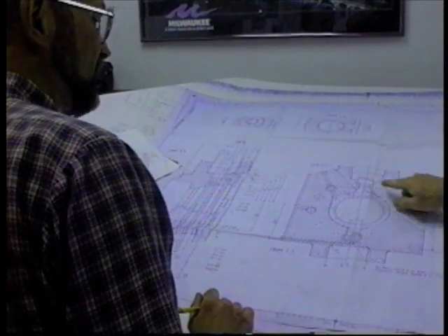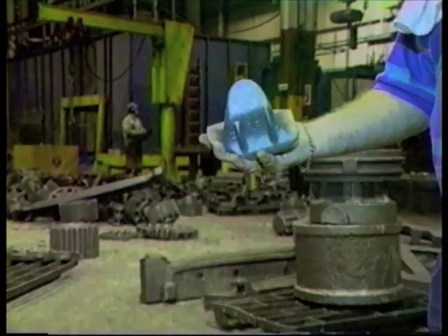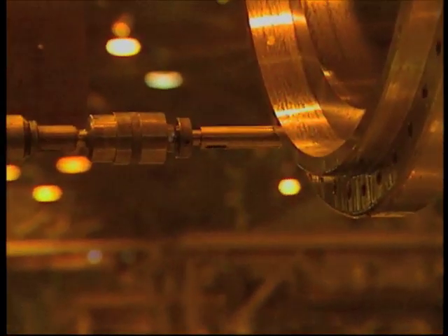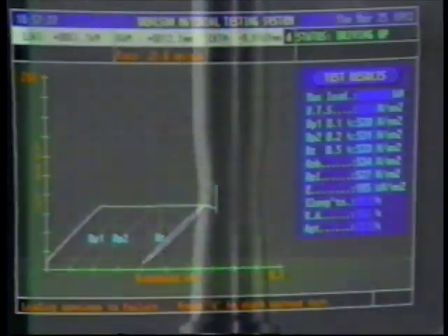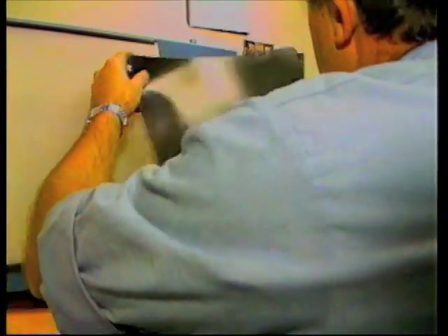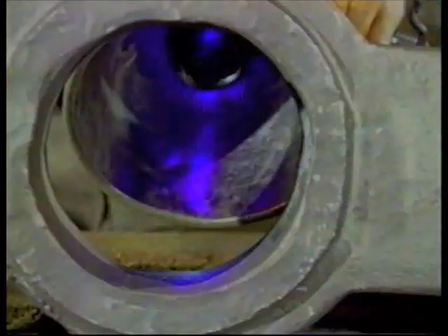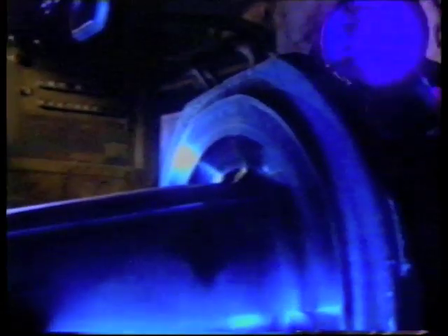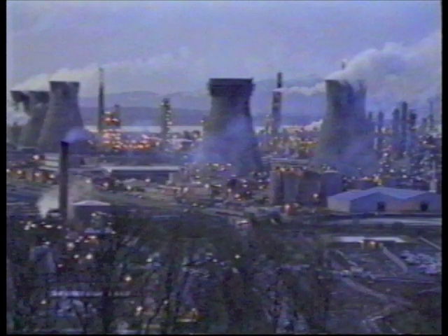Many people are familiar with structural steel shapes commonly used in buildings, such as I-beams that are formed through rolling mills. The same good engineering properties are obtainable in steel castings. And like wrought steel products, castings can be welded, heat treated, and machined. The quality of the steel is tested through chemical analysis and mechanical properties testing of each heat. Modern non-destructive testing methods include radiography, ultrasonic, dye penetrant, and magnetic particle inspection that enables steel castings to be applied in the most demanding applications, such as nuclear power plants.